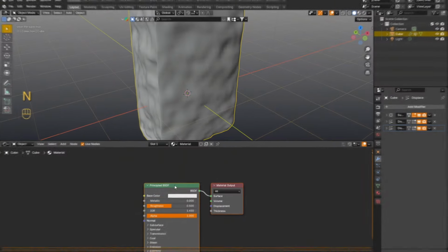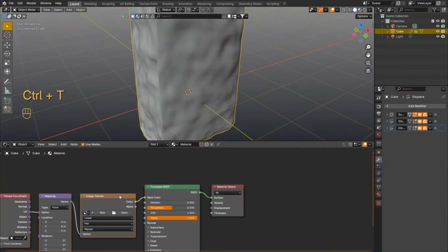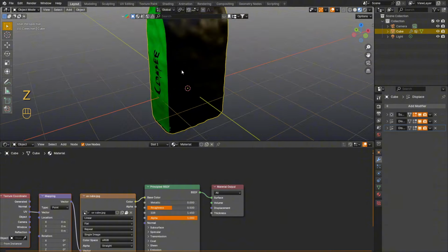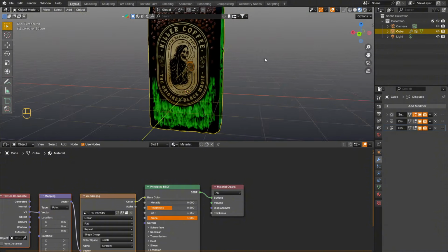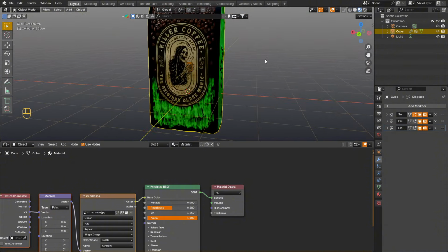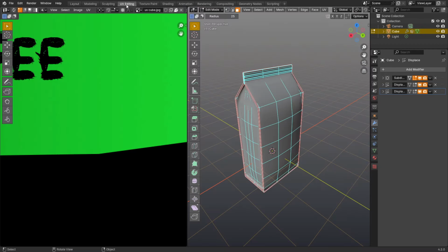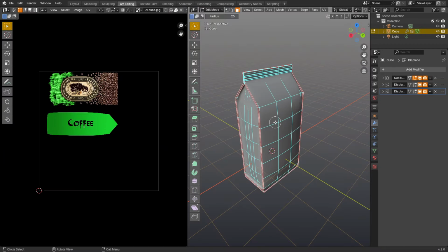Whoosh, and we're back in Blender. Go to Shader, add new material, point to Principled BSDF and press Ctrl T. This way we quickly add texture, image coordinates, and mapping. You must have Node Wrangler add-on enabled. Find our UV map on disk.